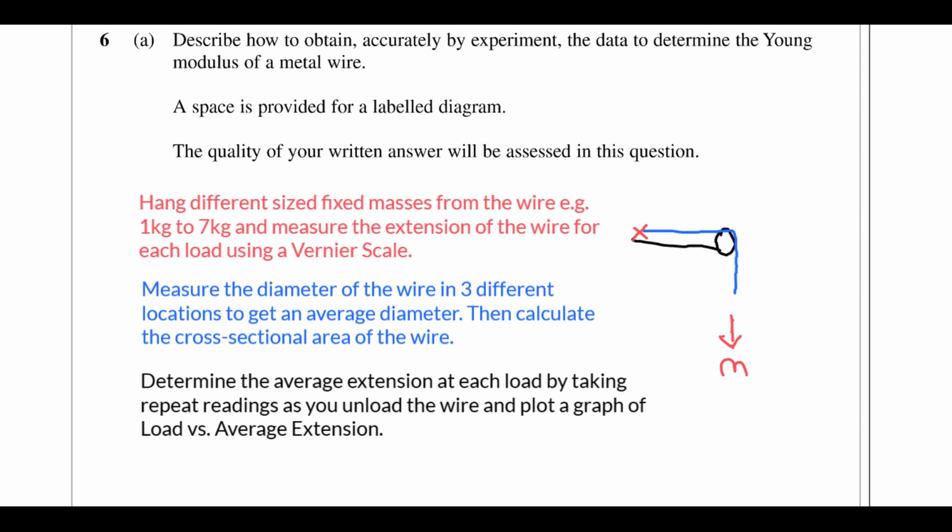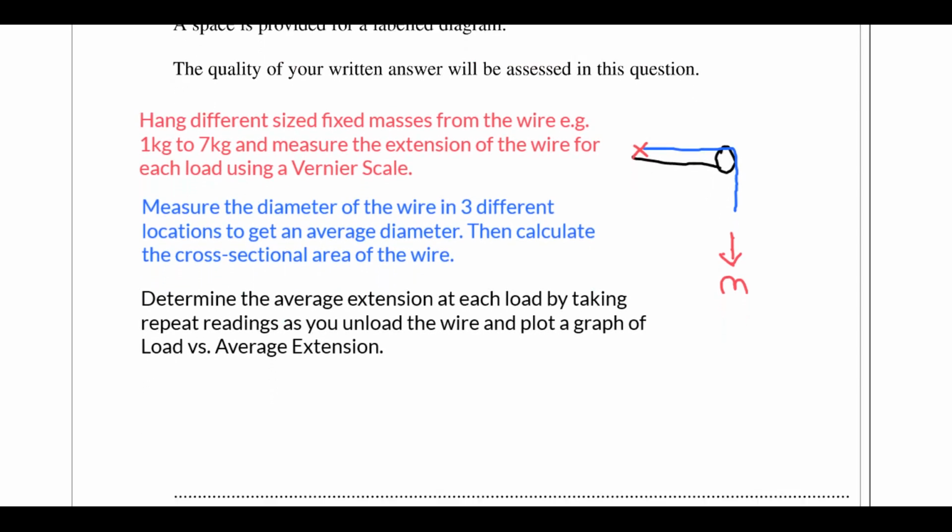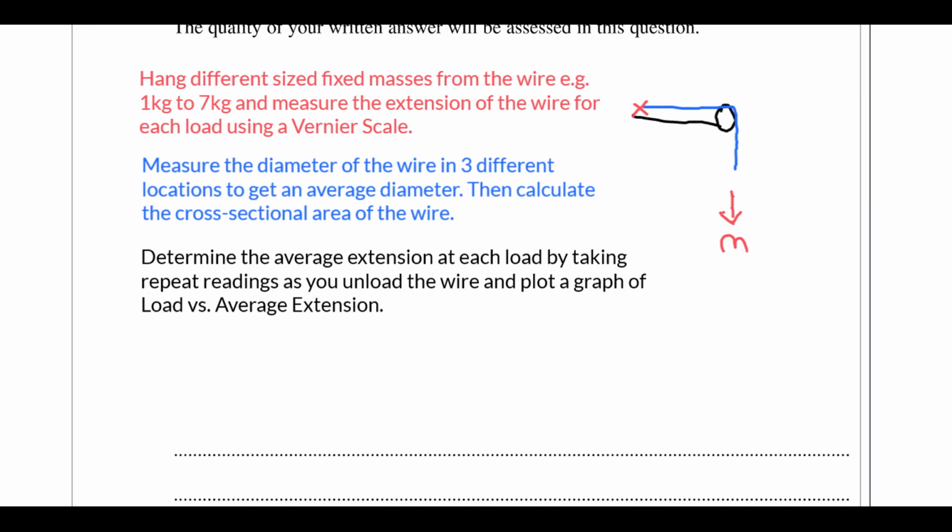So we look at our equation for Young modulus, which is stress over strain. That's force divided by area, over extension, which I'll put as an x, over original length.